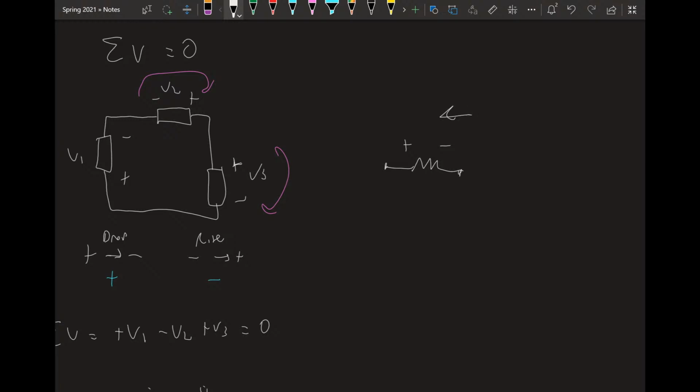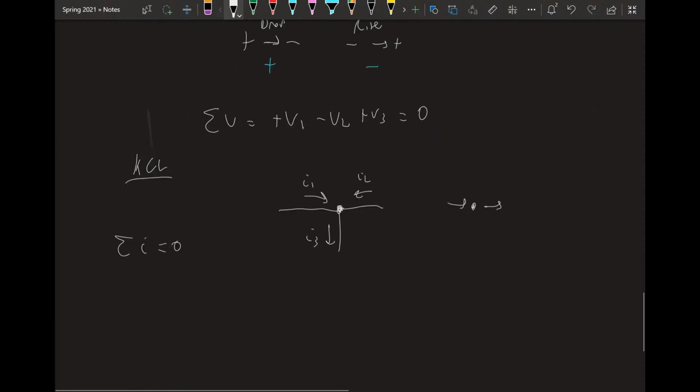The math should turn out that I'm going to get a negative voltage here. So what my math will tell me is that the voltage from A to B is negative, which means it's really a positive voltage going this way, like it should be. So your math should correct your mistake. So the answer is label it whatever you want, and your answer should turn out the same. Just keep your labels there so the negative makes sense. You can't flip-flop. Just keep it there. If that answers your question, you can say so.